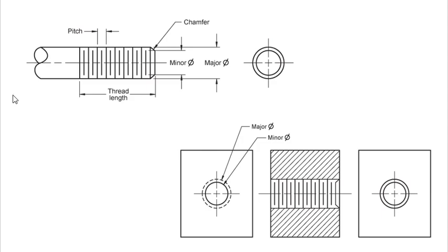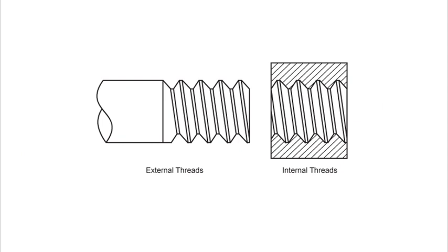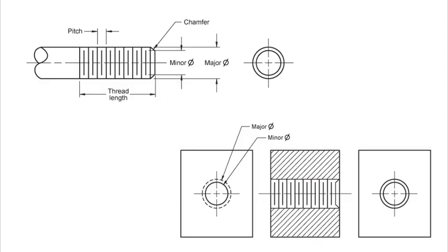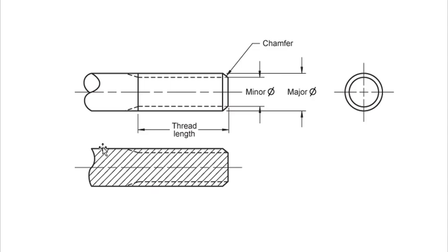And see how different, three different ways of drawing the same thing, yeah? Detailed, schematic, with the stagger lines. And of course, here we use visible and hidden lines to show the minor and the major diameters. So you've got to know the differences. But your exercise is not on the differences. You have to think about the pros and cons of that. So give me what you think. I'll give you the exercise at the end of this lecture.